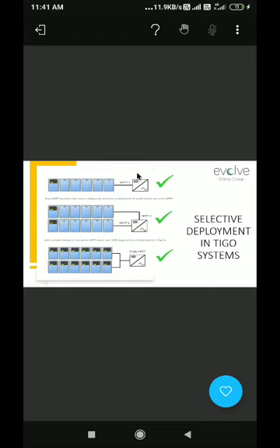Yeah, we have the answer. First, we will look into the first thing. The inverter has only one MPPT and only one panel falls under a shadow. So it is optimized with the Tigo optimizers. So whether it is a single MPPT, blindly you can install an optimizer only on the panels that fall under shadow. No need to worry about deploying optimizers on all the panels.